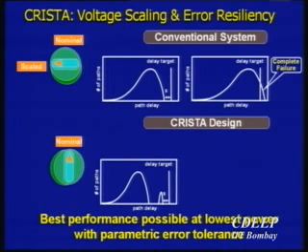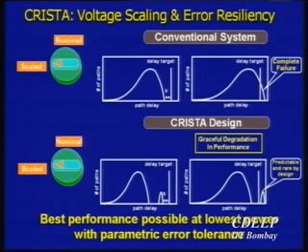So what I'd rather have is something a little bit different. If I could somehow manipulate my design in such a way that I have a path delay distribution which looks somewhat like this, and again it's a cartoon and I'll show you some examples, remember that there is a set of paths which are long paths. If I scale my supply voltage down and these do not meet my performance criteria under the VDD scaling, the question is, can I run these circuits at half the frequency? Meaning that if this set of paths is predictable and rare by design, and it's very important to understand that these have to be predictable and rare. Why predictable? Because I need to do 2-cycle operations for these paths. I'm not going to do 1-cycle operation; I'm going to do 2-cycle, multi-cycle operations for these paths. And rare because I don't want this to happen all the time. So that's exactly what I'd like to do, if I could do it.